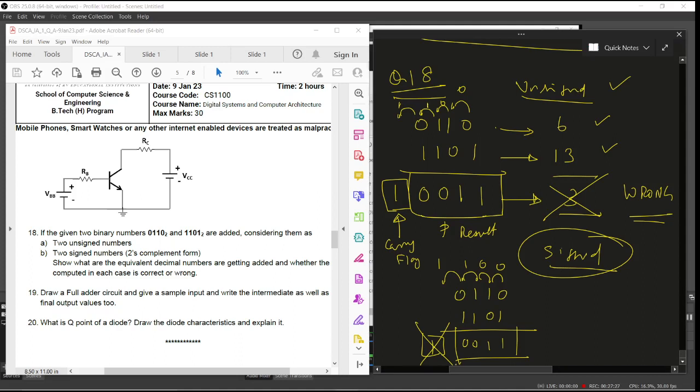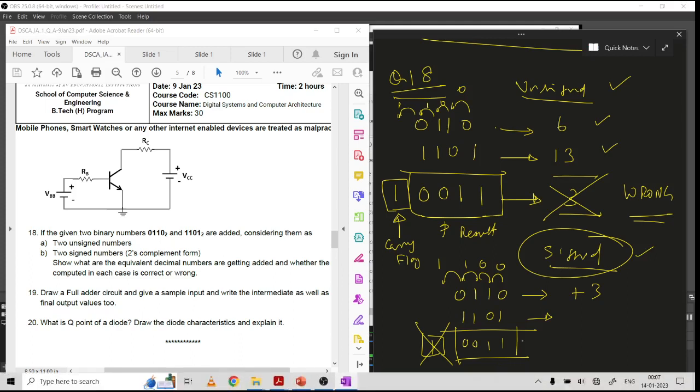Now what are the representations of these numbers first? Let us look at that. Addition has been performed by the circuit, and we have also done it with our knowledge of binary addition. This is again a plus 3, whereas 1101 is going to be considered a negative number because we are doing signed arithmetic. So when interpreting it, we interpret it as a signed number. Now what is the equivalent value of this 1101?